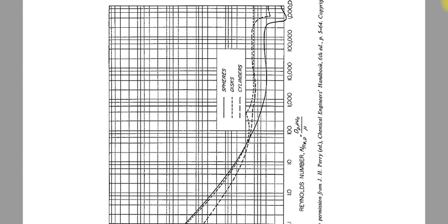It is a very important question and several times asked in the exam, what will be the value of the drag coefficient when the Reynolds number is between 1000 and 3 lakhs. So this is a very long range, and for practical purposes you will generally get the answer in this region only. So in this region the value of drag coefficient is equal to 0.45. After that it will decrease suddenly, when the Reynolds number is more than 3 lakh.